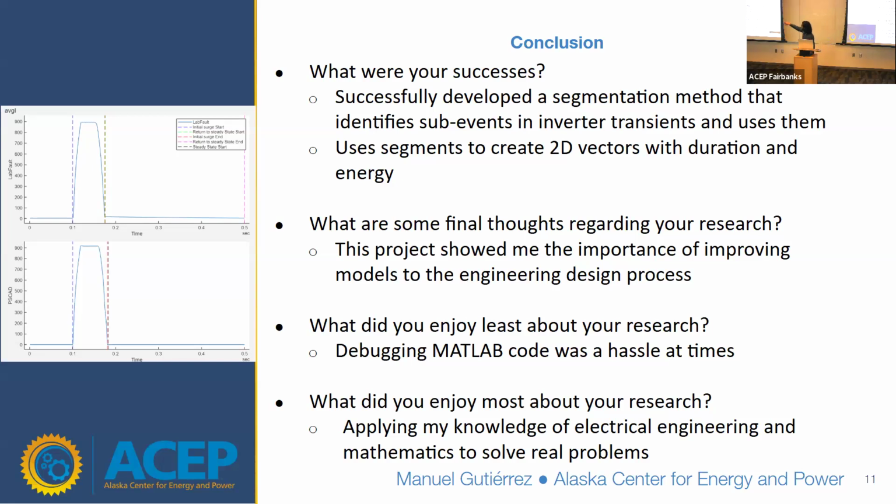On the left there is the current graph for the experimental inverter, and under it is a PSCAD graph. The PSCAD and the Power Factory one both did the same thing. They went out of baseline, they recorded a spike, and then they went back to baseline. We can see that in the experimental version, there's actually a recovery period where, while it's not a spike, it is still returning to a steady state. These are the types of assumptions that the models make that make the engineering design process difficult.